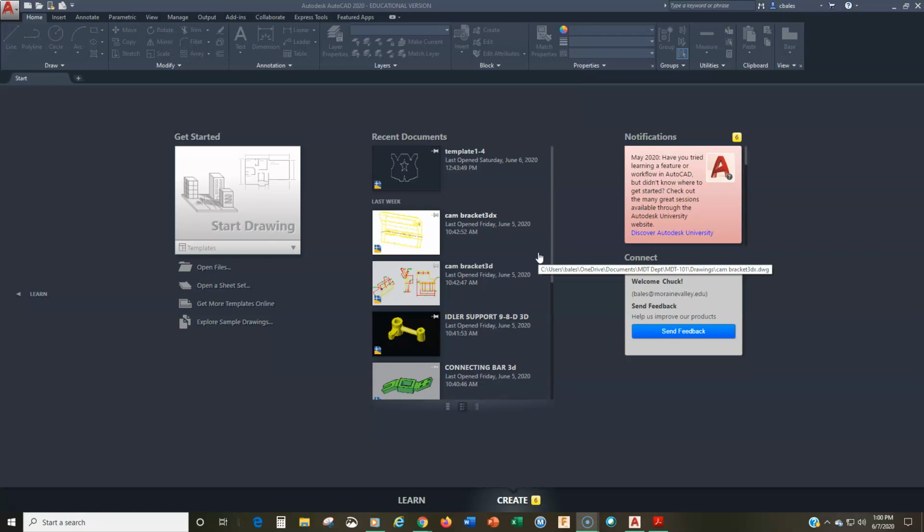First is the construction line command, a new line command. And the second is a circle option, circle tan tan radius, or circle tangent radius, also known as circle TTR. We'll look at both of those in our drawing. This is kind of a short drawing, but it allows us to really focus on some of these techniques, and I'll talk you through it.